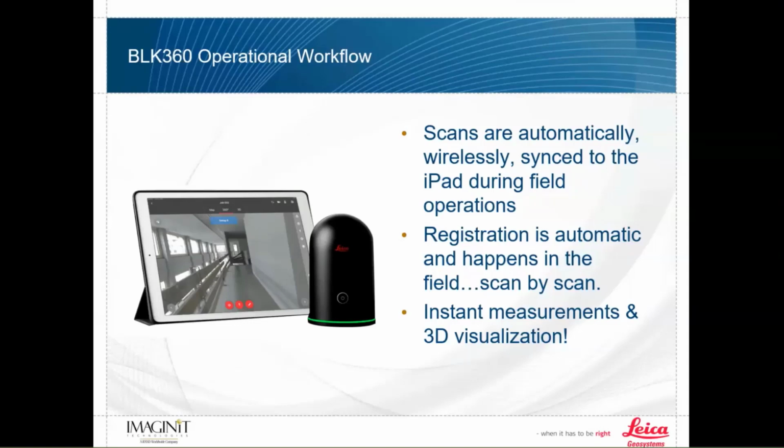But the nice thing about that is we can do that in the field. And with the Cyclone Field 360 app, we can do that through a visual registration. And so scan by scan, as we go ahead and complete our project, our data is already put together, already registered. So when we import, we don't have to do that registration process in the office. It should be already done for us. So we're collecting instant measurements and 3D visualization.